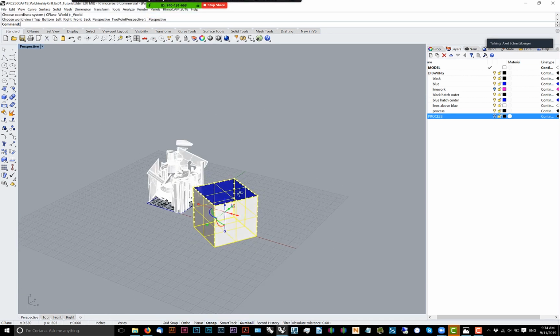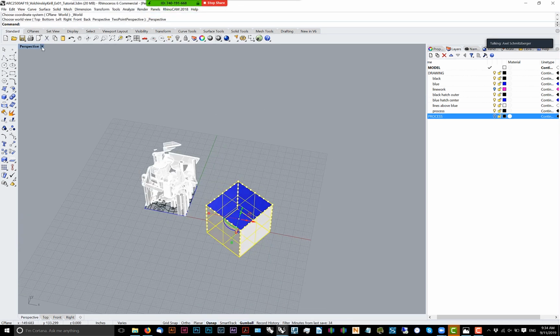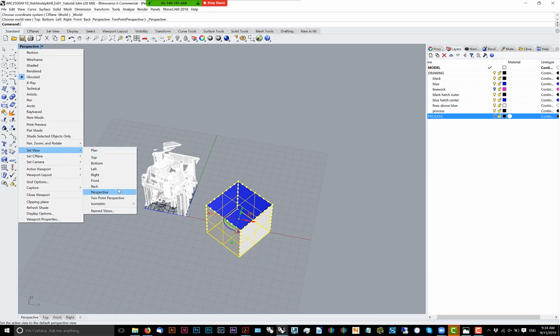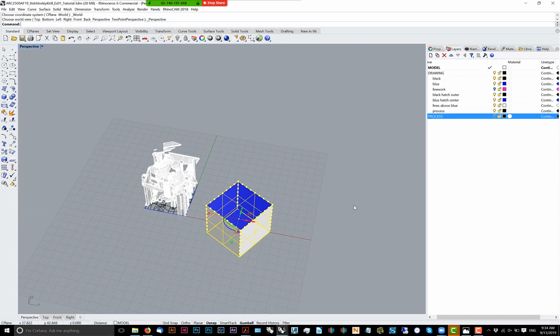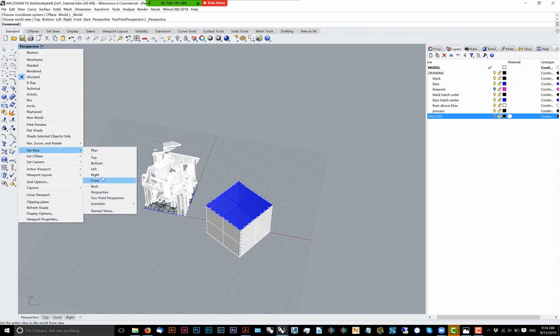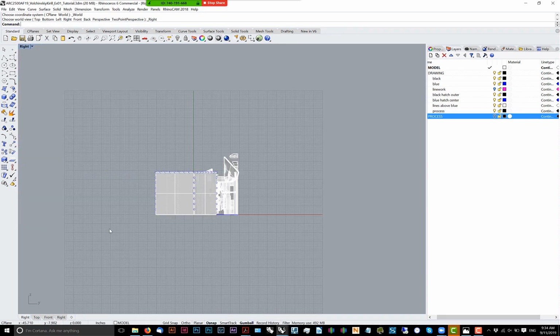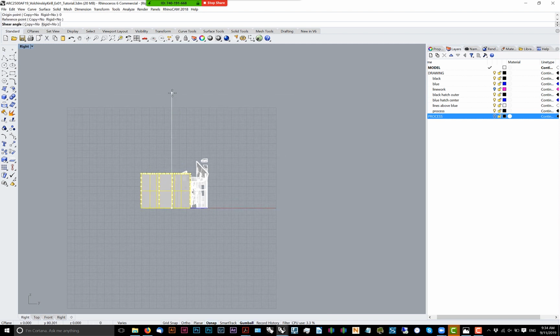And that's basically the result in 3D. It's just a rotation. Then we'll go to the right viewport, looking at it from this side. You can use the SelLast command, select last, if you ever lose a selection, to bring it back. And then we will shear it -45.